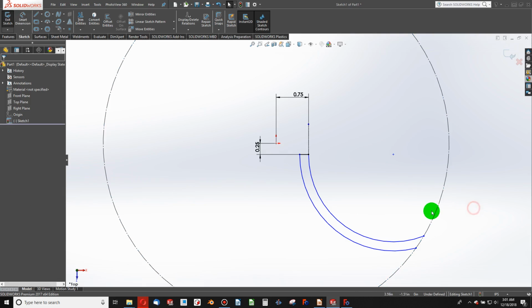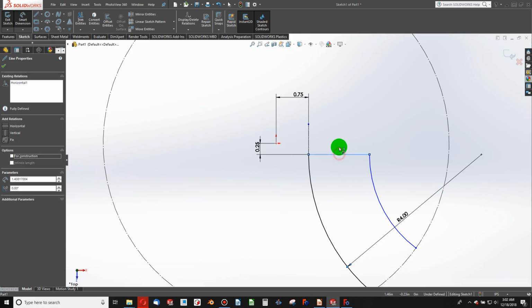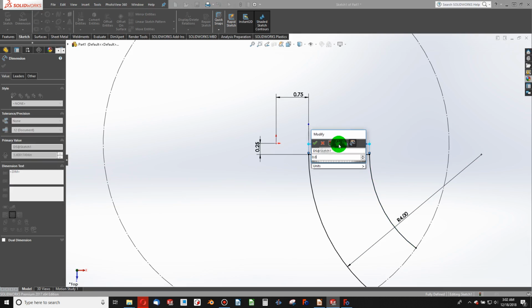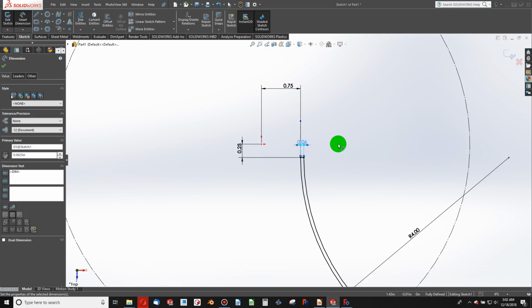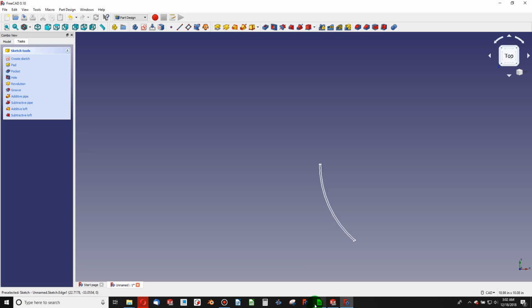Coincident. When I was in engineering school and I first tried this, man, my blades were crossing like crazy. They were touching in all sorts of places, and SolidWorks still ran with it. So it seems like SolidWorks is very robust in that standpoint. So I gave this radius of 4 inches and this 0.625. And we're fully constrained over here. So just to visually see, yeah, looks about the same.